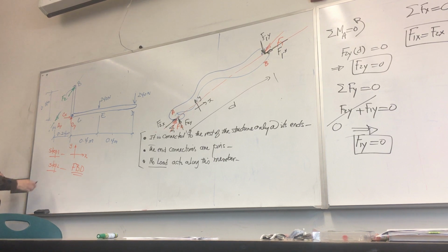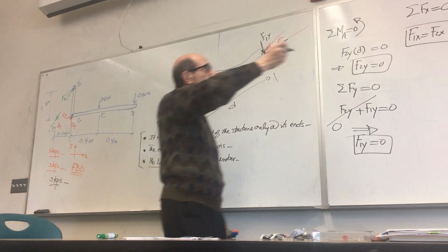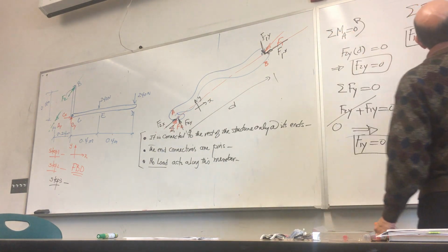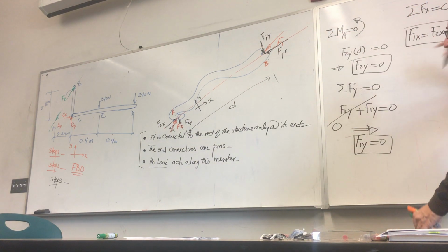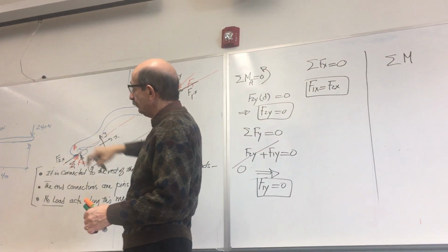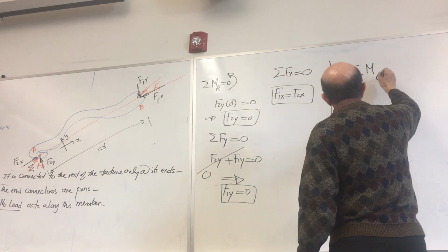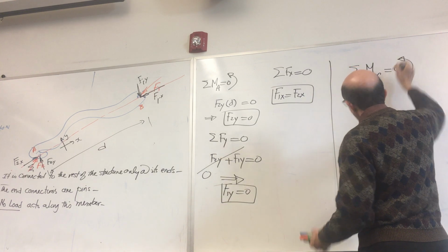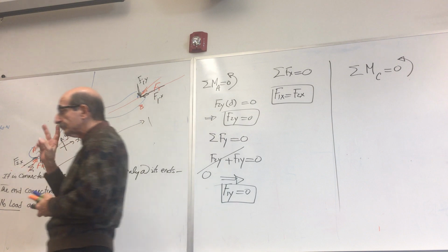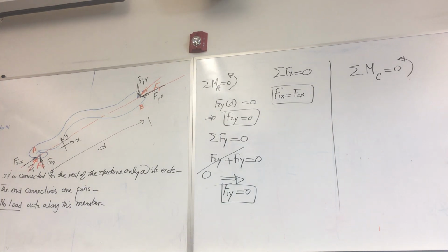And step 3 is what? Equations of equilibrium, right? And I will go here. So I can write summation of moments about a point where two unknowns intersect, and that point would be C is equal to 0. But remember the three things that you always remember. Same polygon, free body diagram, two-force members. That's it. Not much.